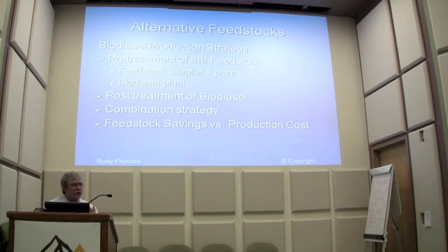Do you want to pre-treat the feedstock first, or do you want to polish and take care of the impurities in the final biodiesel product? That's a decision you have to make. Do you have the equipment to do either one? But most of the time, it's easier to take the impurities out front, out of your feedstock.